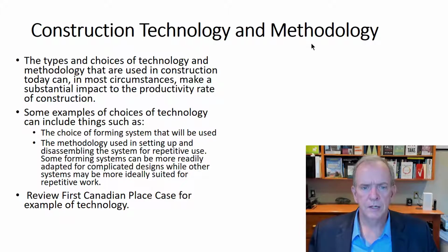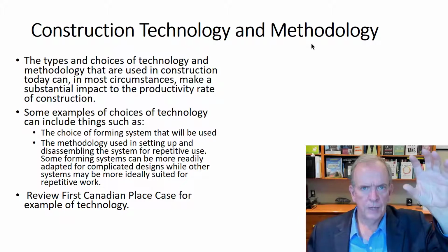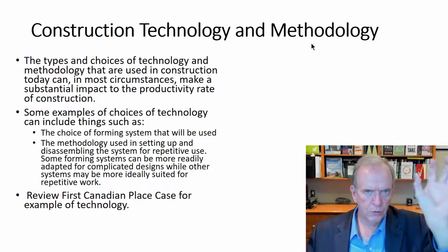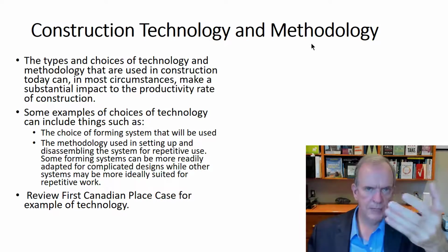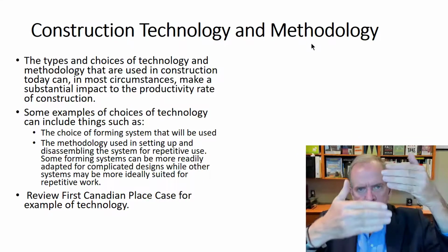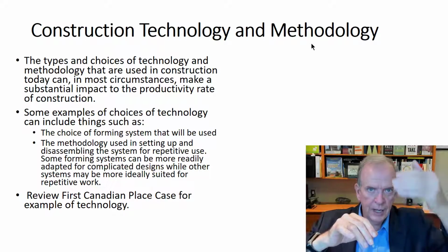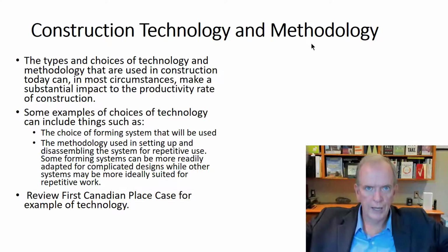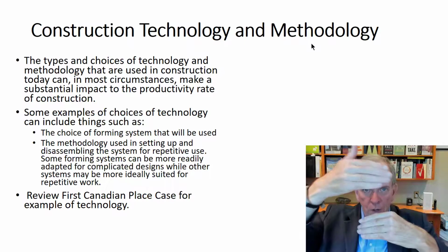And EllisDon, a curtain wall supplier from the US, and the consultants worked collaboratively to come up with a 3-floor system that basically allowed the top floor of the curtain wall, that's the outside cladding of the building, that's the windows, that's the marble, to be taken off. And then after that's taken off, that crew moves down one floor, and another crew starts putting the new cladding on the top floor. So basically all the time you have one floor coming off and one floor going on.